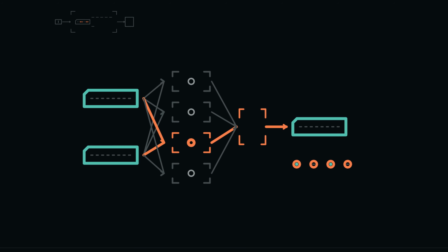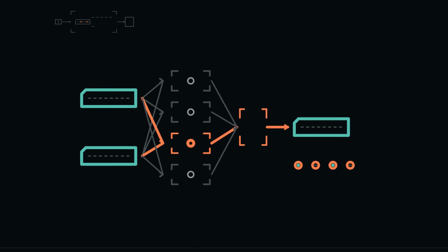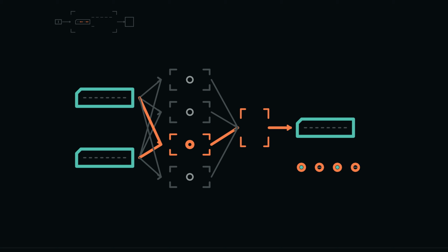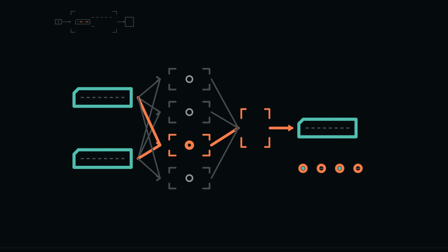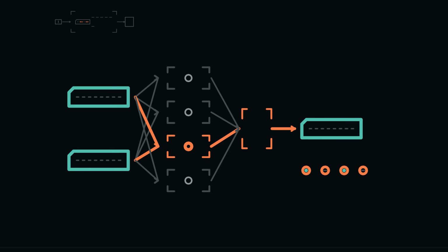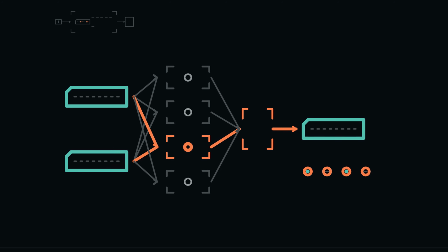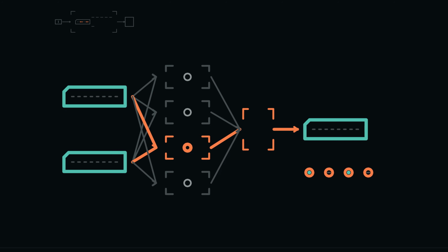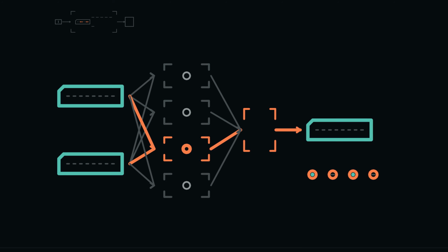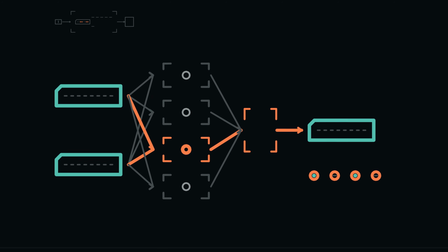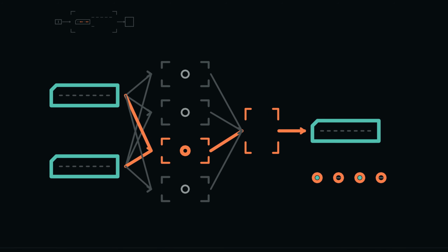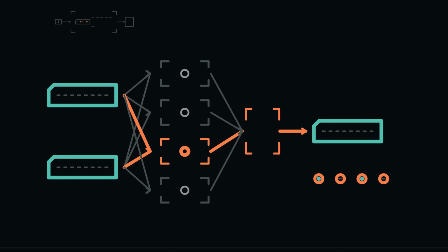Comparison uses the subtraction lane but changes the destination promise. The lane computes a fixed width difference so that the flags can be derived, yet the result selector does not authorize a write back to the source register. Hold R1 at 0 and compare it with 0. The zero flag becomes set, carry becomes set under the no borrow rule, and R1 remains 0. A later branch may inspect zero. This separation shows why an ALU operation is more than a labeled arithmetic symbol. It specifies result formation, flag formation, and whether a register is allowed to capture.